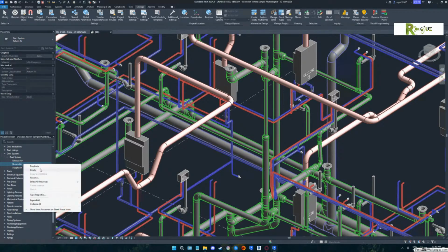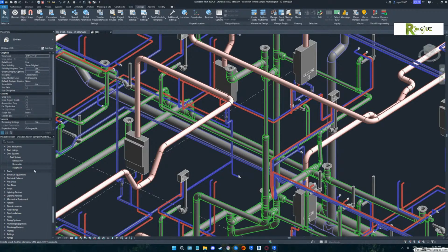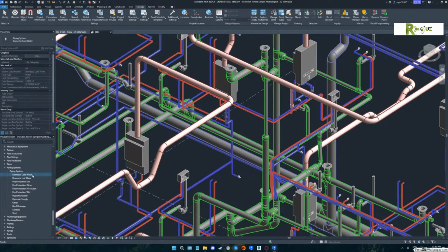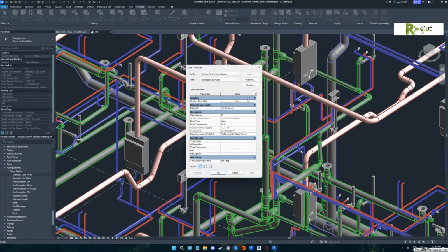Okay. Now go down to pipe systems and hit the plus next to pipe systems. See all those? You should do that with all those. Okay. So click on it again, copy, and then you go into it, and then you can just use a paste. That'll be your material. You're going to use one called pipe domestic cold water. Actually, it should be called plumbing, okay? Because this is the plumbing file.